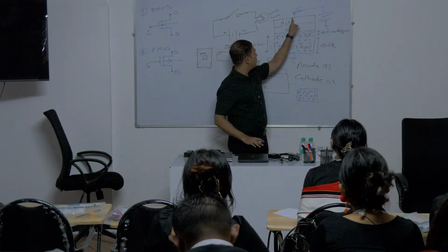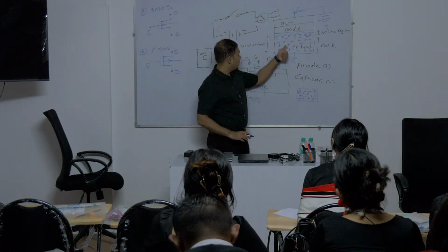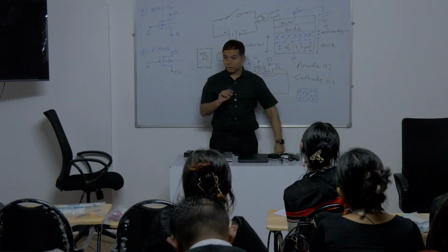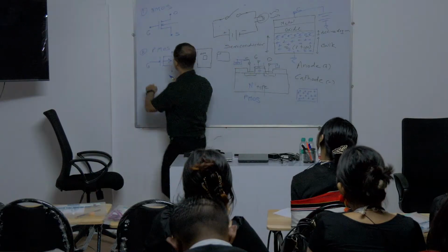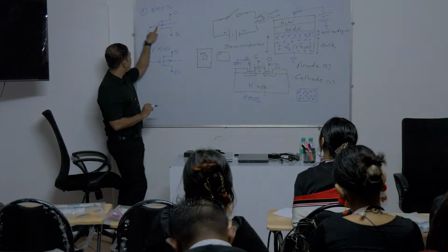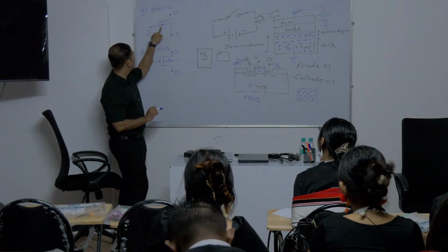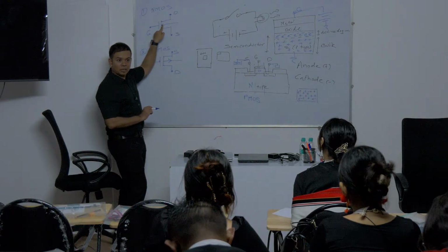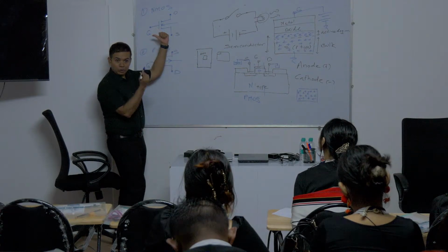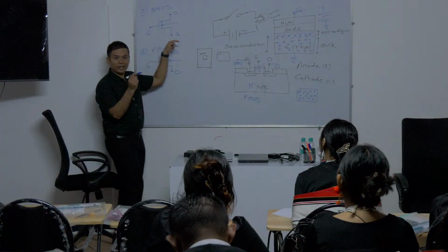When I apply a positive gate voltage, the electrons, which were initially like this, started to move upwards. Yes or no? So similarly, just think about it, this is the gate. We consider this as metal, in the center oxide, and then this is the channel region. Understood? So electrons are moving towards the channel. Yes or no? That is why this arrow indicates inside.